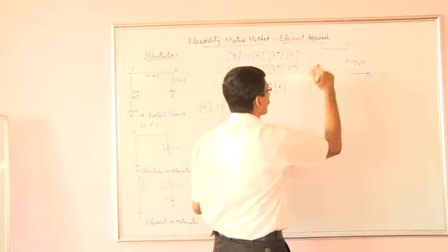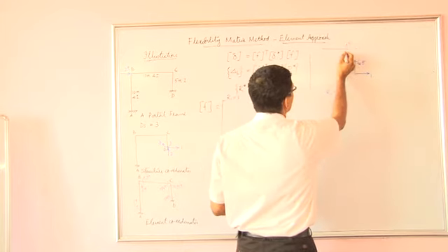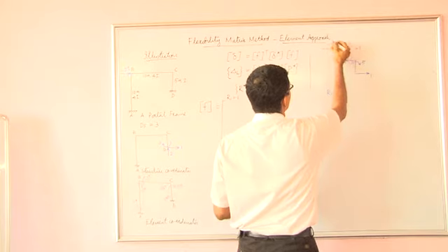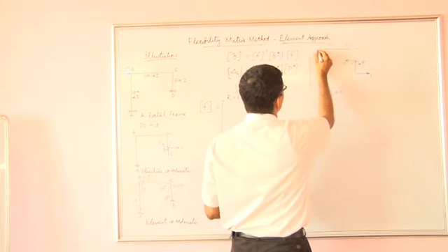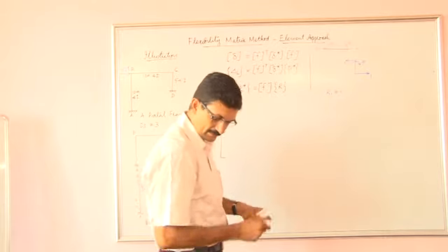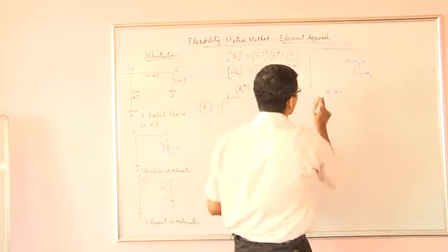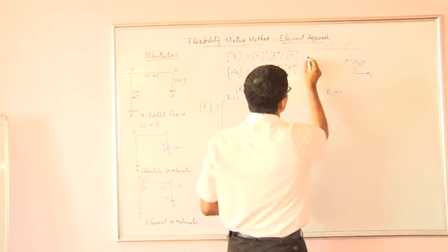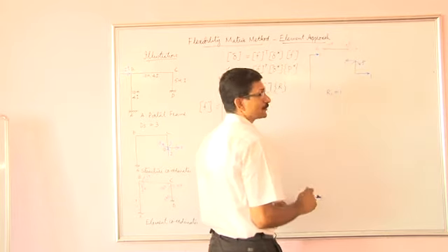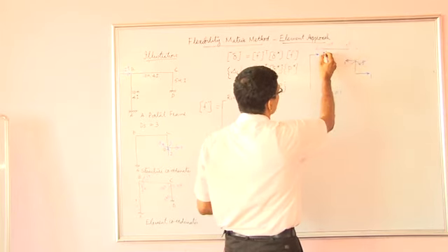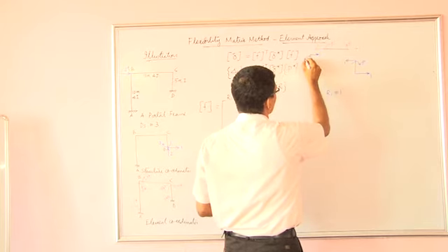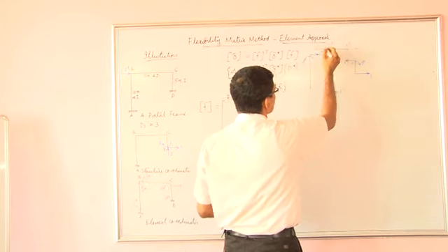Again in the beam, for equilibrium we will transfer this force or this moment with an opposite sign here at the other end. So this is 5 kNm, and this force will be 1. So equilibrium of that beam is also satisfied. Further, when you come to this column, at this joint the force here will be 1 rightwards for force equilibrium of the joint, and this moment will be transferred to this member as an anti-clockwise moment equal to 5. So joint equilibrium is also satisfied.